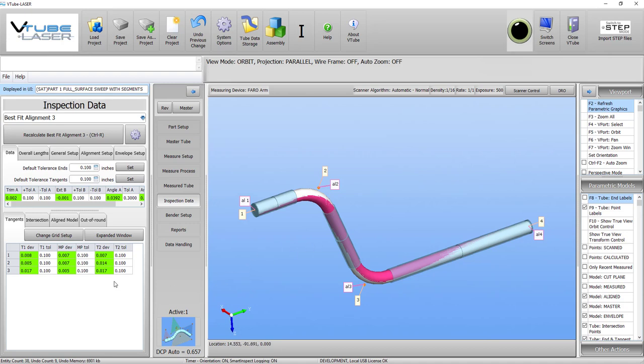And this is probably a little tighter than you would normally get on the first correction, but I would say you might get something that is around double this, depending on your setup, how good your setup is, and how new and how well your bender bends. In this case, for a Unison bender, it'll bend really well first time when it comes to correction. They're very good at correction. You're going to see data that comes well into the green very quickly. And in this case, of course, we're way under tolerance.